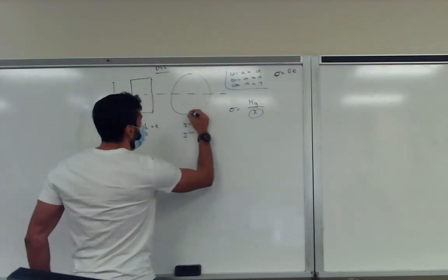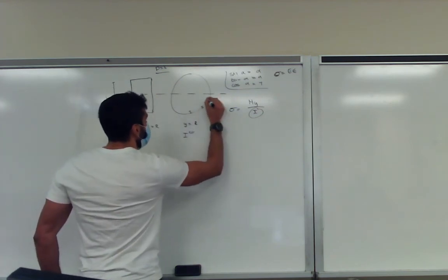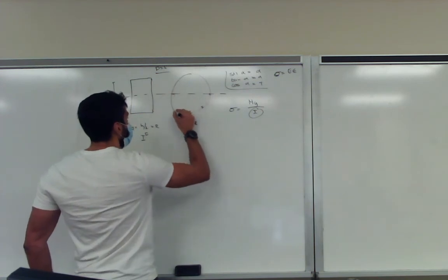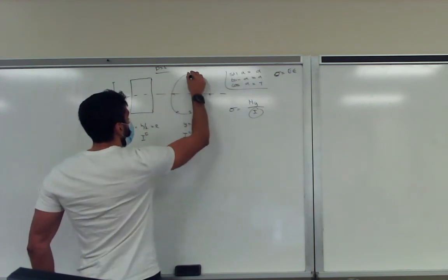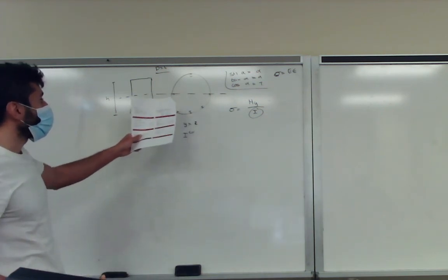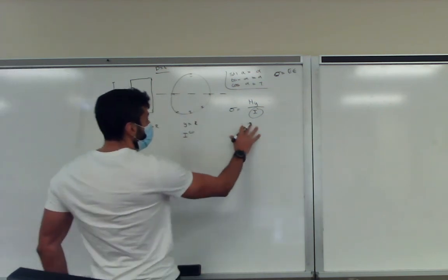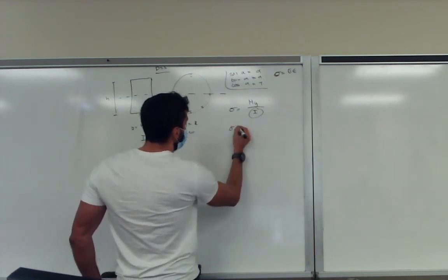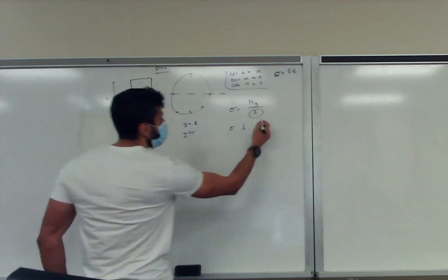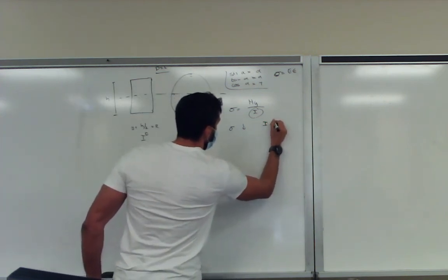Last lecture, we said we can add stiffness to it, similar to just increasing the moment of inertia. So without changing our geometry, we can change the value of the moment of inertia by adding stiffness to it, and then we can get our stresses to go down since our moment of inertia value increases.